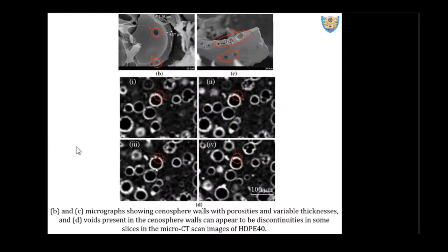Why does it happen? What I mean by this is, don't go by only one slice and interpret on that. Take multiple slices and look at that. And why did this happen? There was no crack, a little crack, a large crack, and again the crack closes. Because these hollow microballoons of fly ash cenospheres, which are naturally available, have porosity within and even porosity in the shell. You can see it here, all the marked ones. So your shell is also porous, and that's why this has been used in the cement industry for a decade now, which absorbs the moisture, and that's why we call it pozzolanic cement. It absorbs and it grows and closes all the cracks in the cement structure, and that's how it happens. So when you take a micro CT, please take note of this and have specific caution on that.